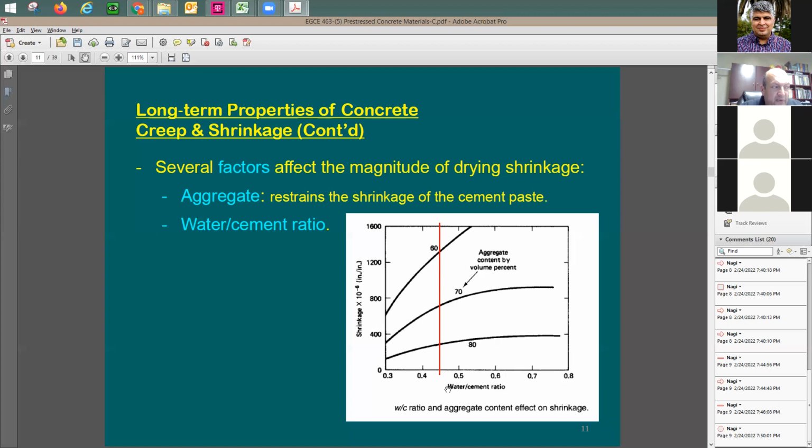Just so you know, if you go here with a water cement ratio of roughly 0.5, if you look at the concrete, you feel it's very solid. And you would say, I cannot really use it. You'd say to yourself, if you look at concrete with water cement ratio 0.5. So 0.45 is going to be very low. And you cannot really work with the concrete unless you put good additives. It's going to be either air entrained or something for the workability, like the WRDA.